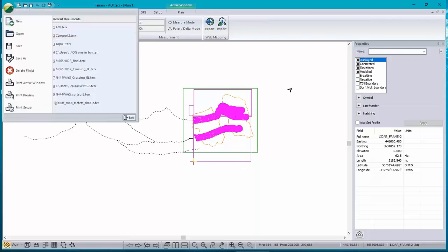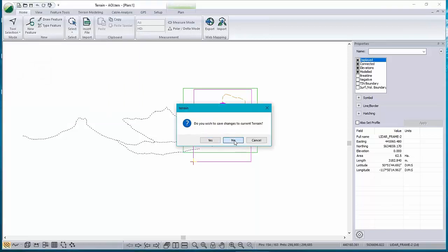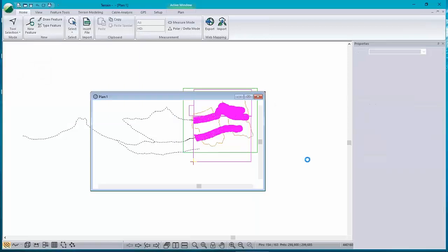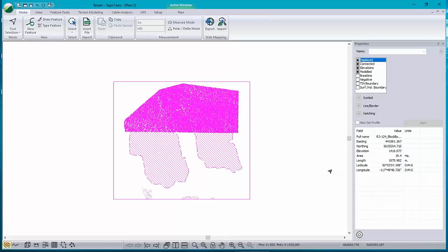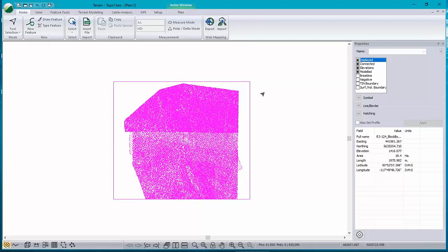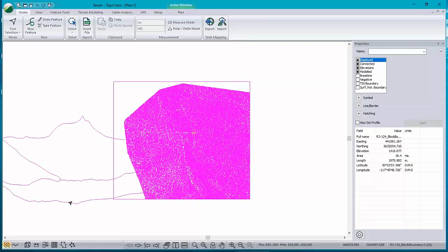That's actually not what I want to use for my surface, so I'm going to open one that I've already created, where I've brought in all the data in this entire region, and I've already thinned it down. I'm going to just open that file. Okay, there we go. In this case I brought in a clump of data, and I thinned it using this square, and whoever created the LiDAR tiles had already chopped off this bit on the edge here.